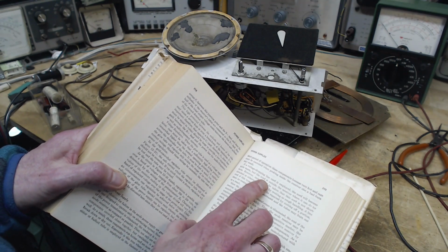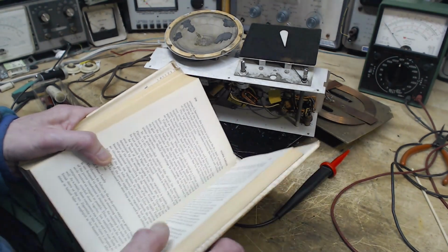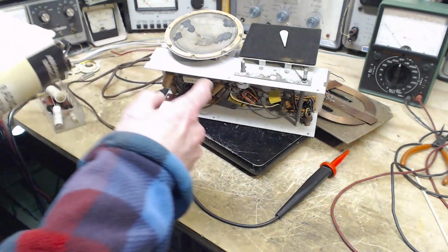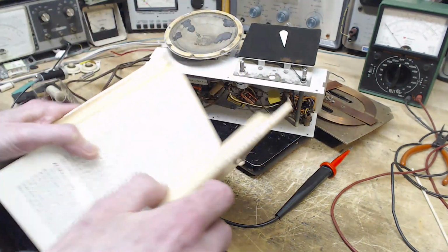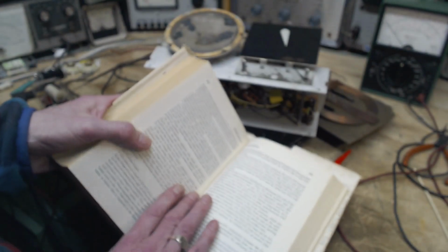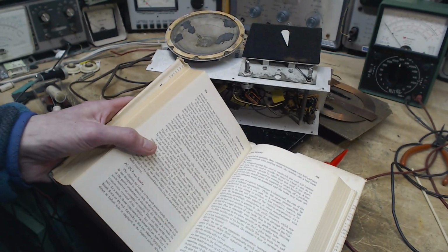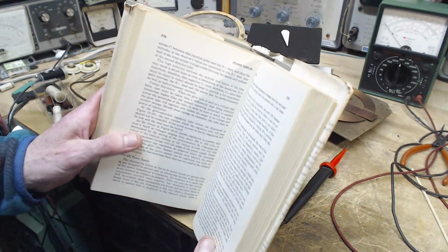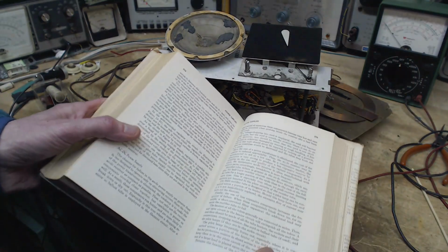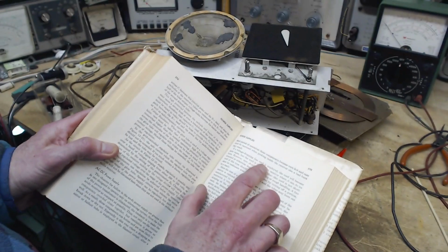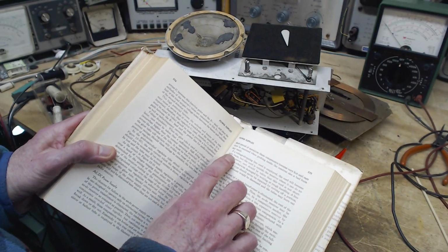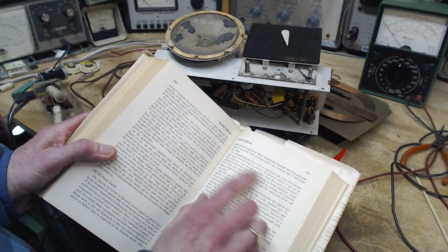If a voltage dropping line cord, did you know that some of these much older radios, the line cord is actually a resistor? It drops the voltage coming to the radio. Did you know that? If you replace the power cord with just your typical power cord, you'll be in trouble. Those are really old radios though. If a voltage dropping line cord is employed, the cord will become quite warm, but the cord is outside the receiver where it can do no harm.